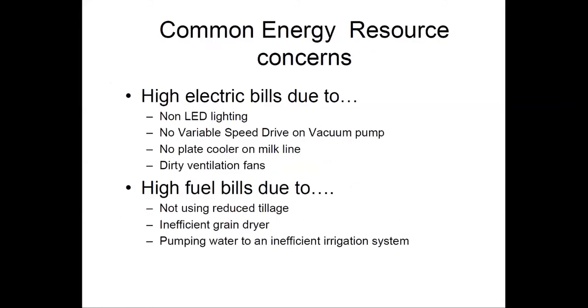Another resource concern that you can think about looking at is energy. As you know, we have a CAP to plan for energy, and you can recommend that they get a conservation activity plan for energy, to take a look at some of the things: high electricity bills, if they don't have the proper lighting, if they don't have variable speed drives on their pumps. If there's no plate cooler on the milk line, a plate cooler is a very effective thing that cools off the milk before it gets into the bulk tank and saves on electricity.